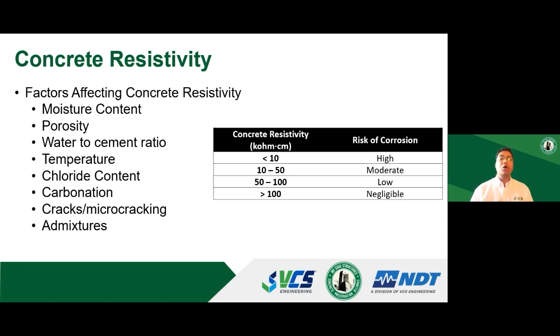But if you do it on a concrete core, then you can have a surface saturated dry state of the concrete core, and you can get consistent measurements constantly. As I mentioned before, if the resistivity is really high, the risk of corrosion is negligible. But if you have a highly conductive concrete or less resistive concrete, then the risk of corrosion increases significantly.